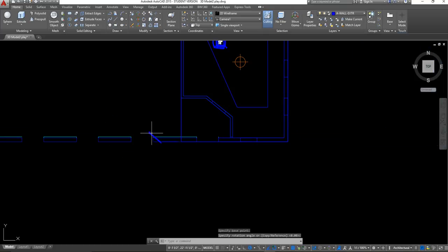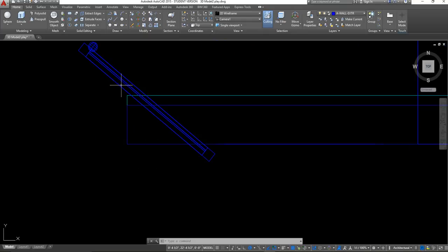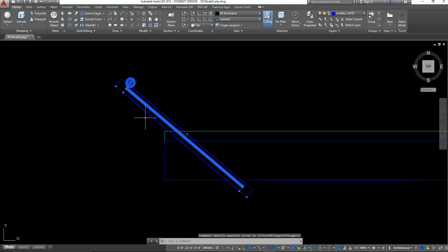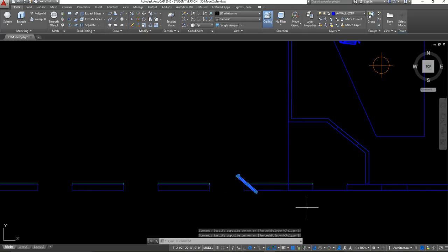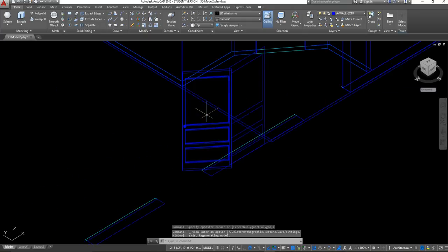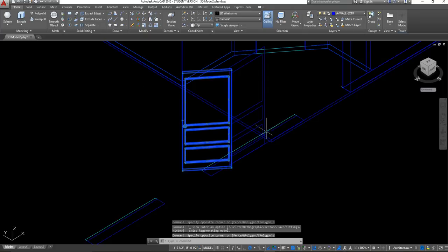And then once I move that door to the place it needs to be at, then I can go back in and rotate as need be. So I kind of got it at the angle it needs to be. So I'm going to select that door again. Okay. And I'm going to see what the best view is to move this door. So I'm going to see if it's better if I do it from my Southwest isometric view. I'm just going to select that door.